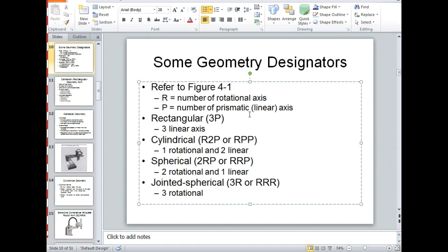So our robot would be a 6R. These robots right here. Rotary. Yeah. So these robots have rotary axes. The only ones right now that we have, some of the robots on the line over there, we have 2 Ps over there. So it's got 1 horizontal axis and then 1 linear vertical axis. So that would be called what we call a 2P.